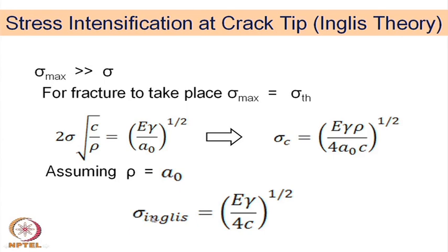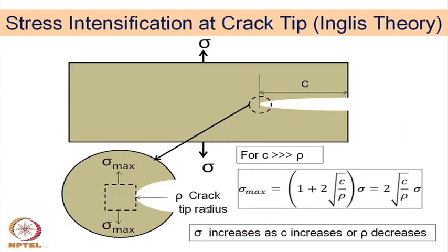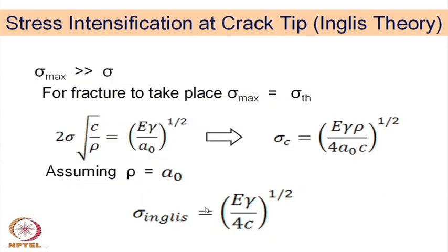So, the longer is the crack, at a lower stress the fracture will take place. So, that is also an important point to note, that it is not only the crack tip radius, but ultimately the crack length is also important here. Although, when you are talking about the stress intensity factor, this crack length has less importance. So, this is how one can calculate the critical stress required for the fracture.